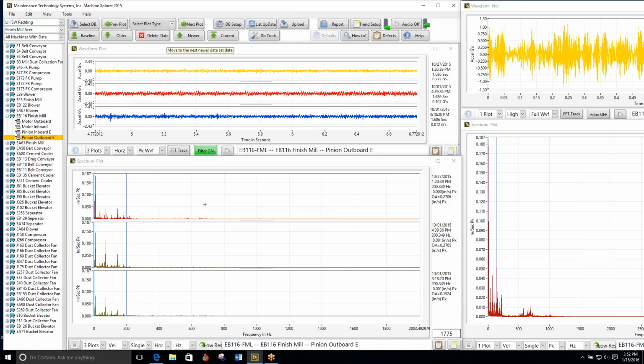This is one that they actually had the bearings start to overheat on them, so they got a look at them, decided that the inside of the bearing was rotating on the shaft. They sent the pinion shaft out and had the bearing surfaces redone and put a new set of bearings back on it between the yellow data and the red data.